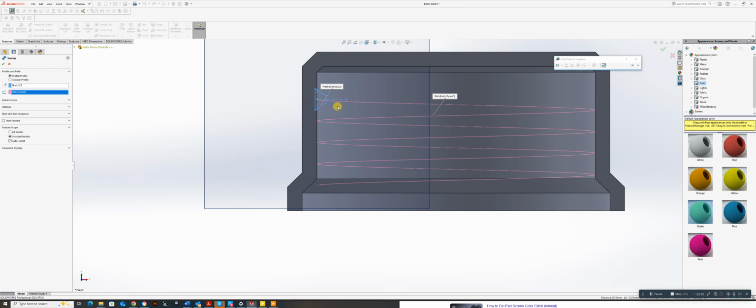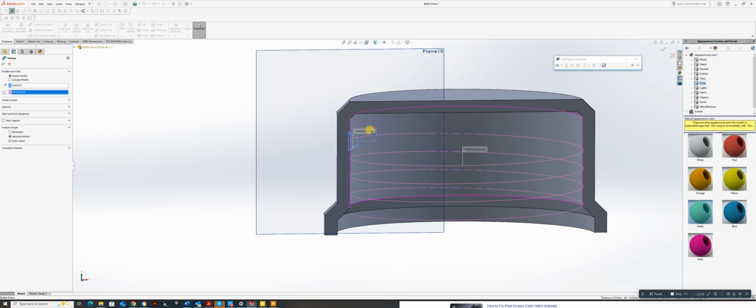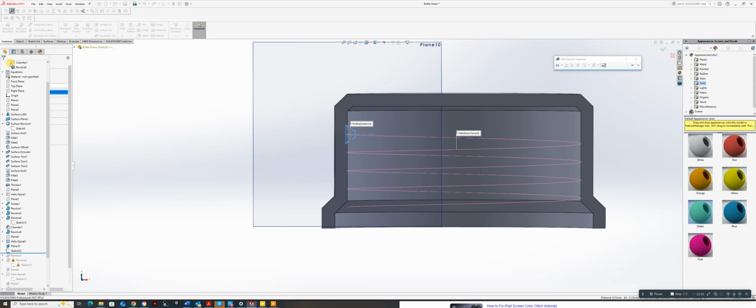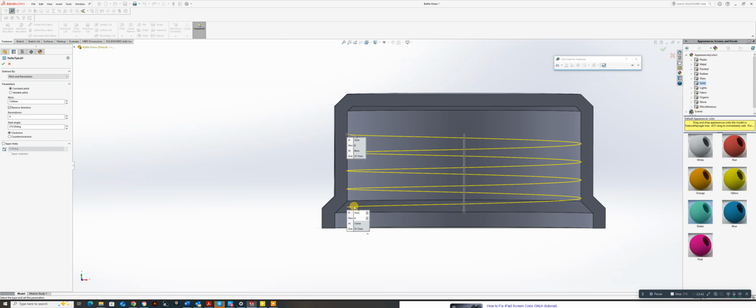Okay, so why is that not going to follow that path end? Tangents. It might be because it's got... right. That's why, because it's got nothing to go onto there. That's why it's failed. So let's just go back. Let's go into the helix. Go to edit. This doesn't matter if this is shorter. You can see it's dropped off the end. I didn't see that because the bottom's away. So I'm just going to go to revolutions and go up, down, just so that comes back in. Go to there. Now this should work now.